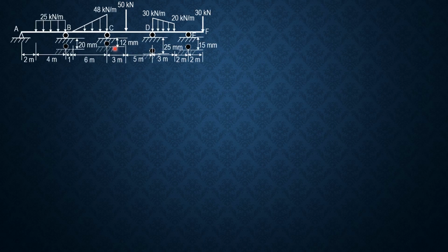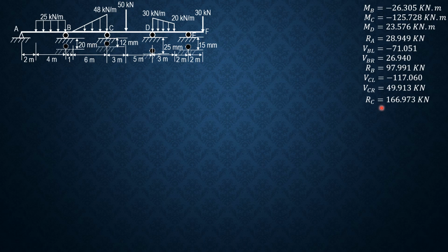So this was the beam, and these are the results up to R sub C. Then we have to apply moment at C and moment at D to continue. Let's compute shear at D just to the left this time. Reactions. Shear at D just to the left, summation moment, consider CD. We sum up moments about C equals 0.